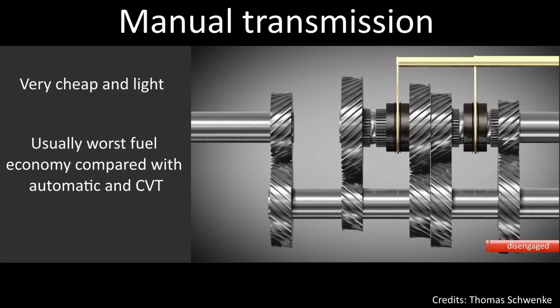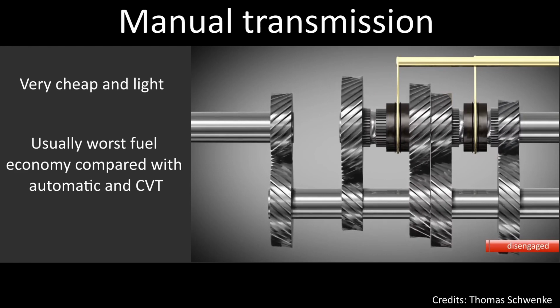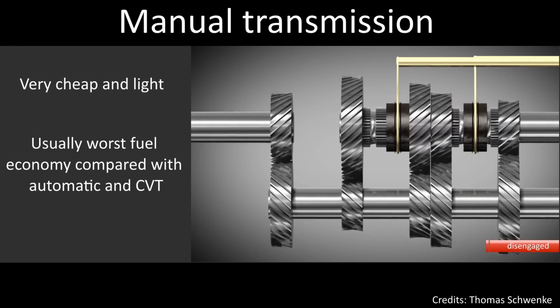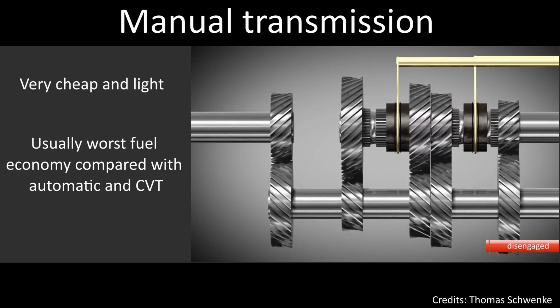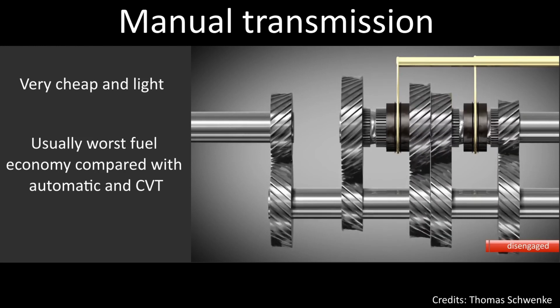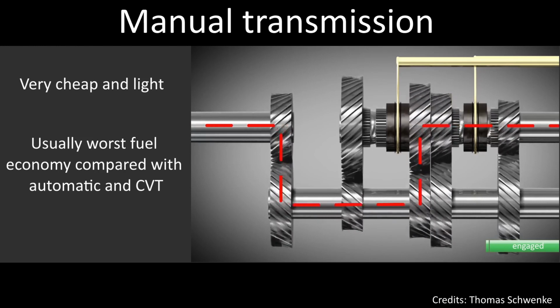Meanwhile, if a change of gear is necessary, it's sufficient to disengage the clutch by pressing the clutch pedal, then select the gear needed using the gear stick, and finally release the clutch pedal. In doing this, you have changed the transmission ratio and so the vehicle can deliver the perfect torque also for different speeds.